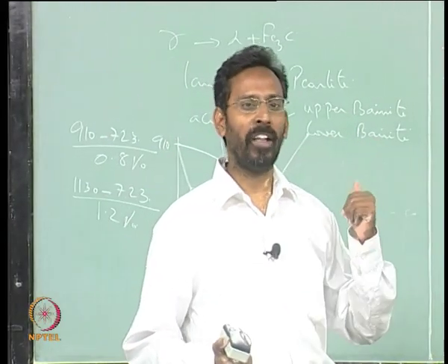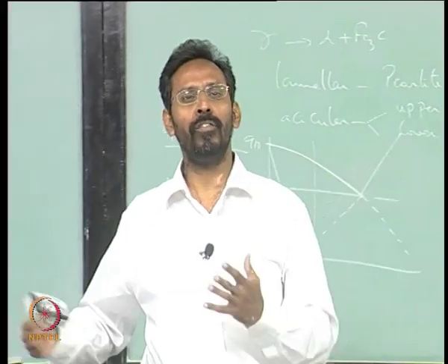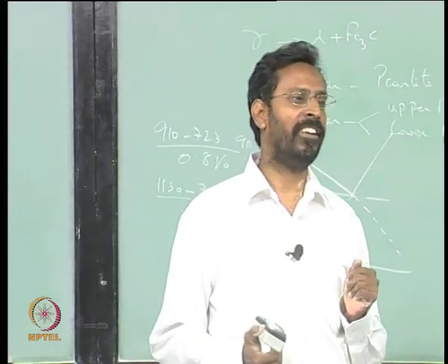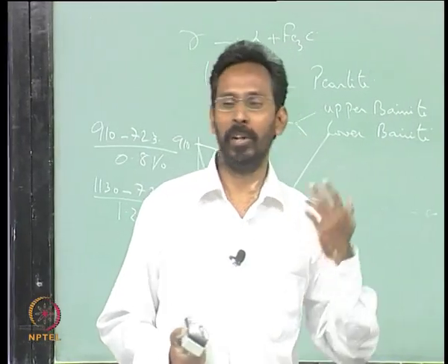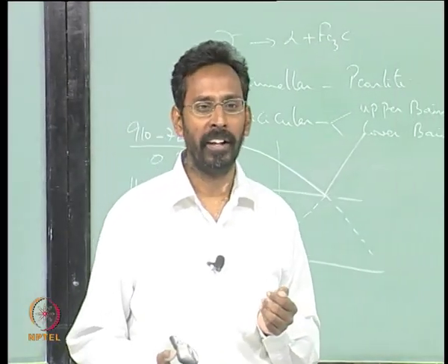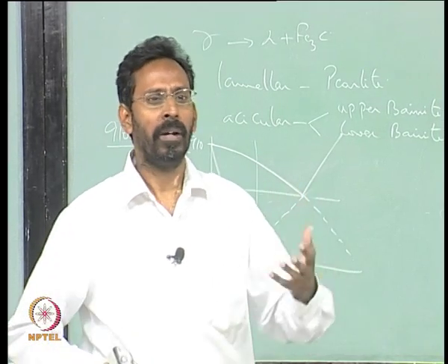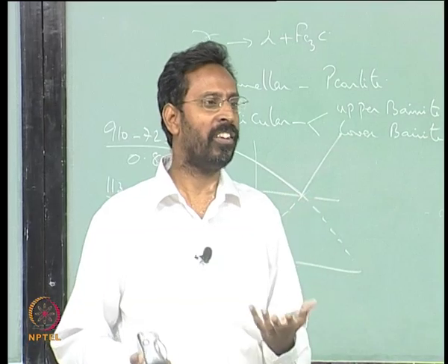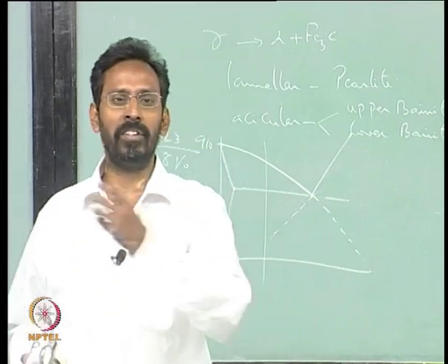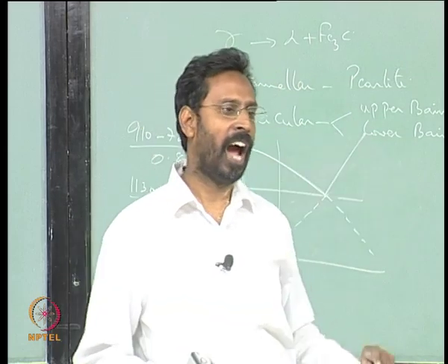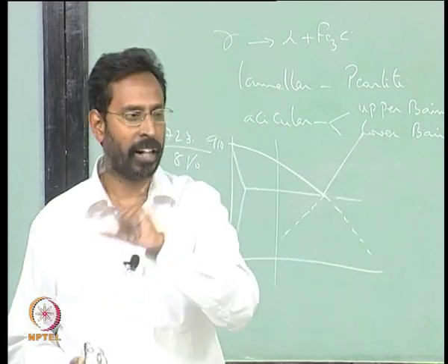obviously the pearlite formation, it is like when we talked about glass formation we said every liquid would form a glass unless crystallization is intervened, this is what we said. Turnbull has made this statement long back. Liquid wants to become a glass because it has no problem in becoming a glass, because its structure is the same, but unfortunately some crystallization is coming in the middle. If I can suppress that crystallization I will get the glass.